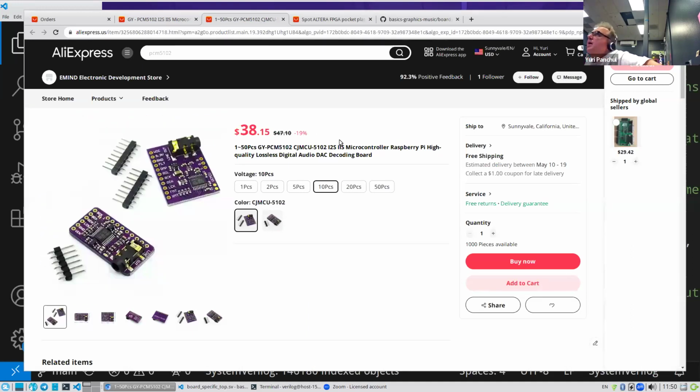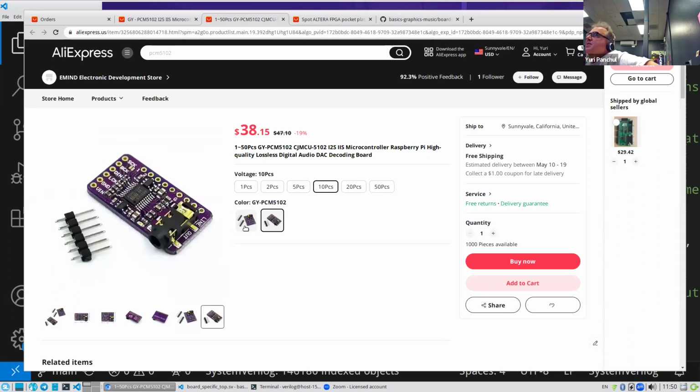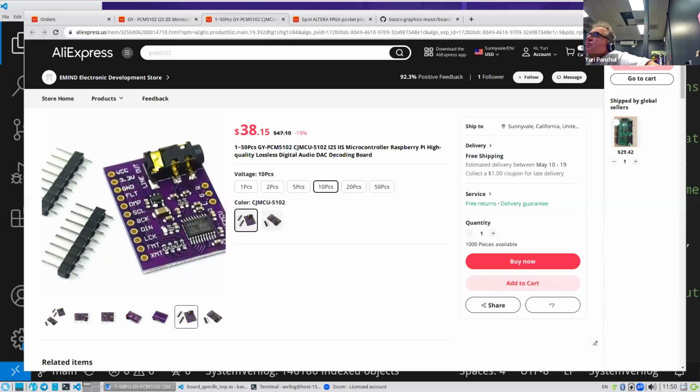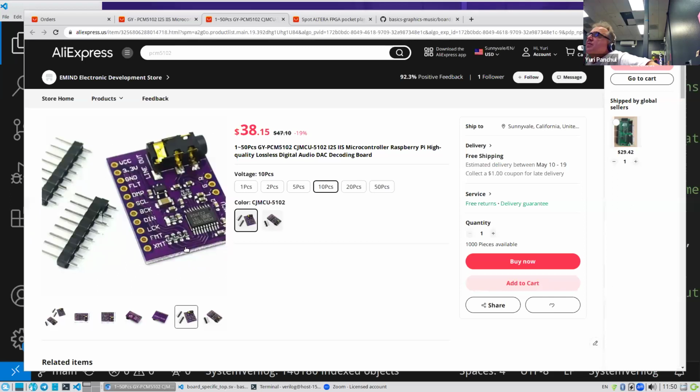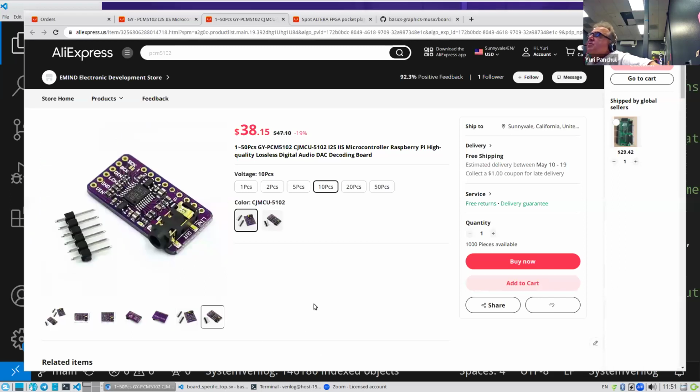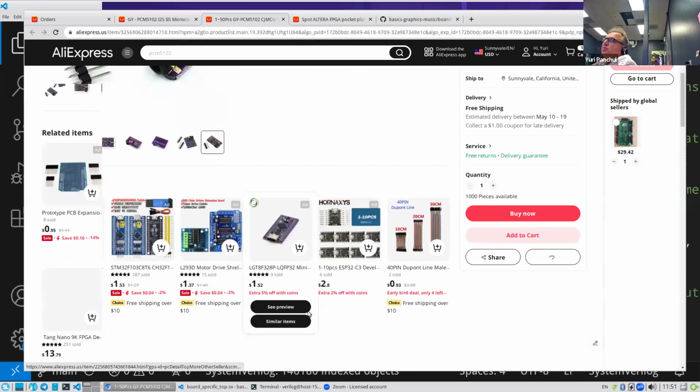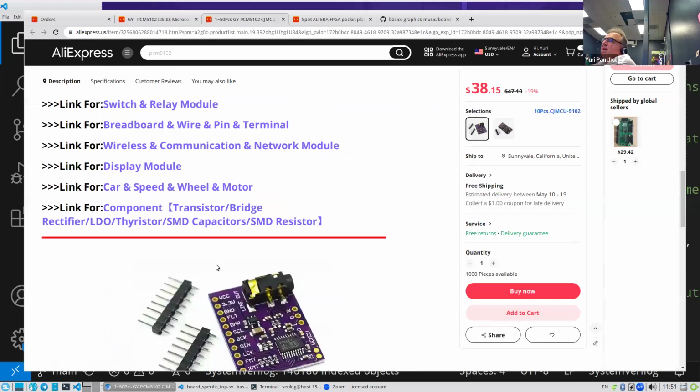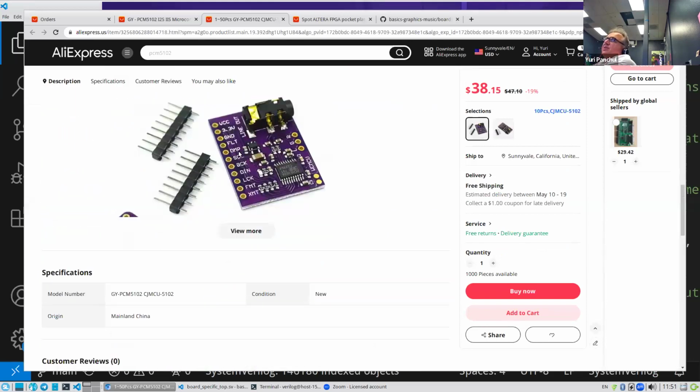Yeah, so they're using a chip called PCM5102, and such boards are used frequently with a Raspberry Pi, so they produce good quality of sound, and it is not too loud. However, as you can see, it has many pins additional to the pins of a regular I2S protocol.